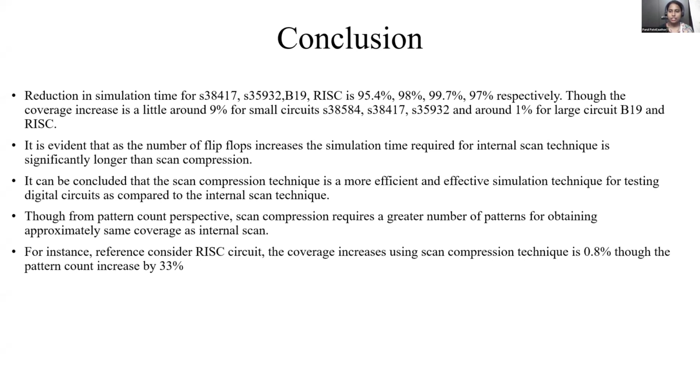For memory testing, there's another architecture which is embedded in the design. So just to let you know, not all the flip-flops in the design are converted to scan cells. So it's partial scan insertion, we can say. Next, it can be concluded whether scan compression is effective.